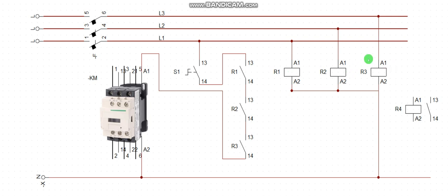Now, as you all know, a relay is composed of a contact and a coil, both of them embedded. But when we are carrying out our design, we detach the contact from the coil, take the coil to one side where the output is going to be inserted, then take the contact to where the input is going to be inserted. That is how we do schematic arrangement, all right? So this is the form of a relay. So let me take it away.